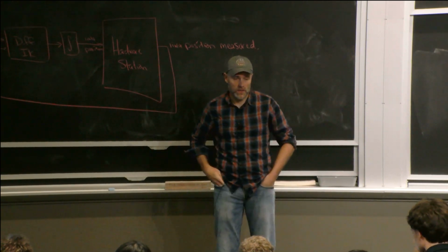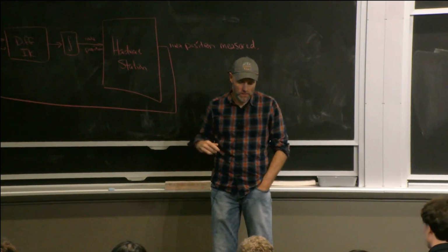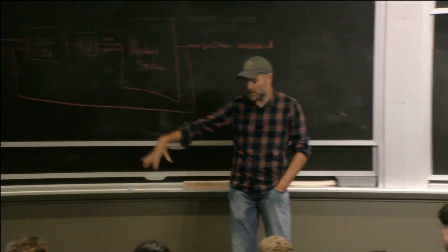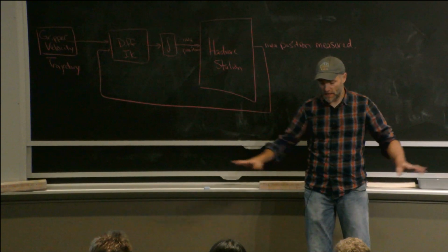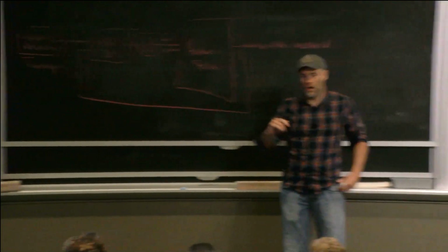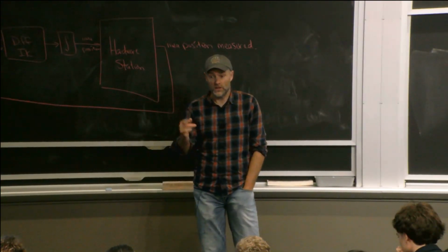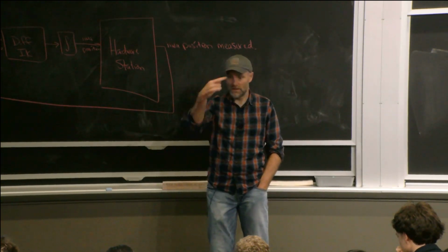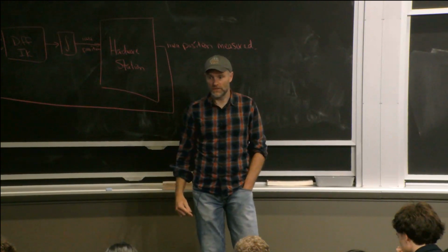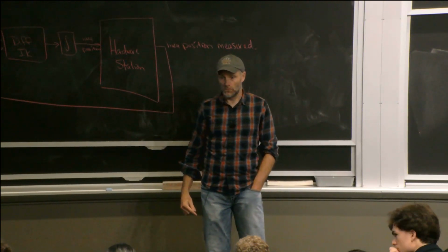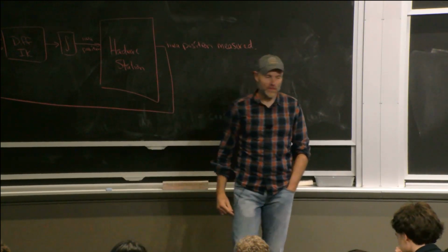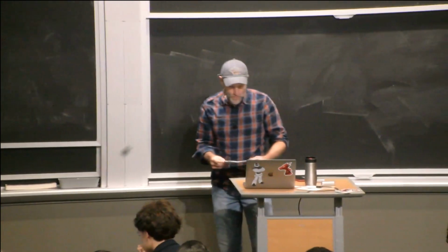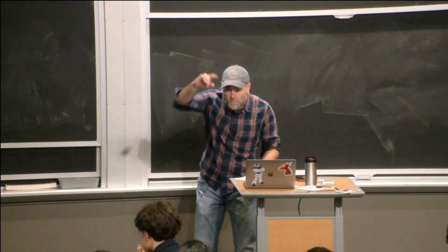The second question was about the LiDAR on Spot. Typically the Velodynes on a car or on Spot. The Spot I brought did not have a Velodyne on it. It just had the surround cameras. But yes, typically those are scanning LiDARs, and you have to do some careful work to think about blurring from fast motions and timing it with the spinning laser. That's true. I think Spot's pretty good.